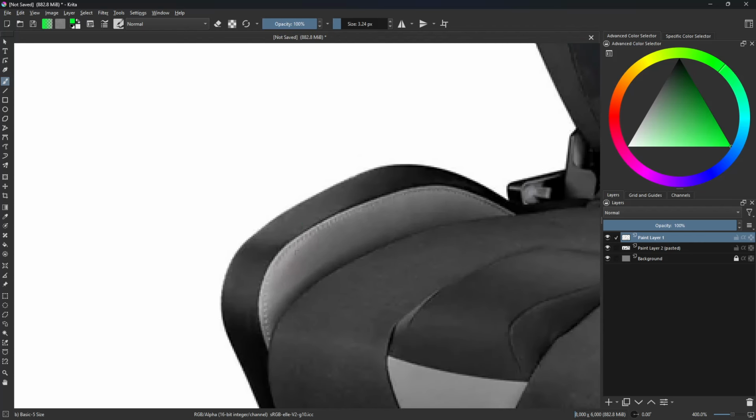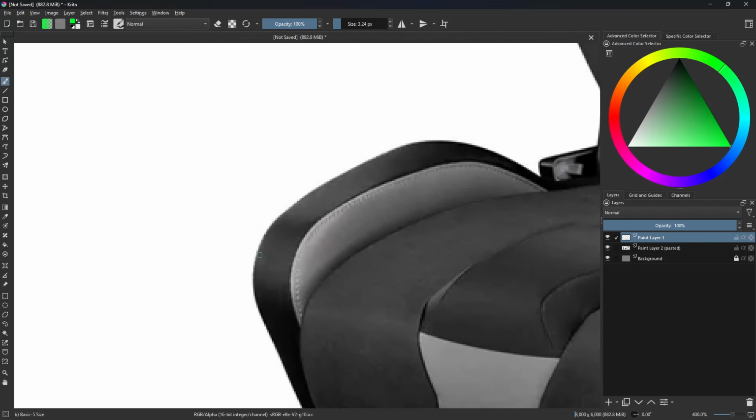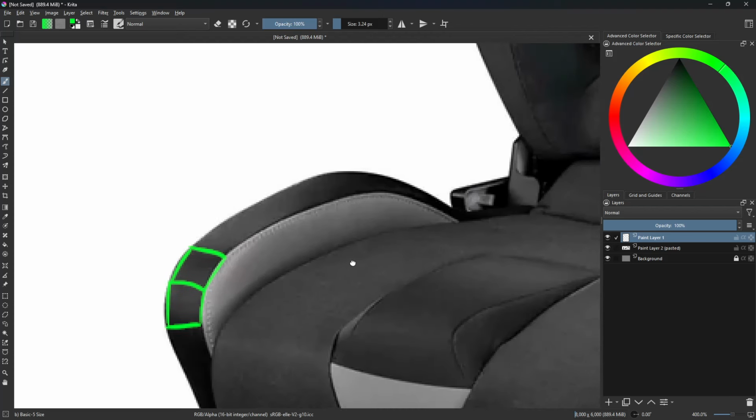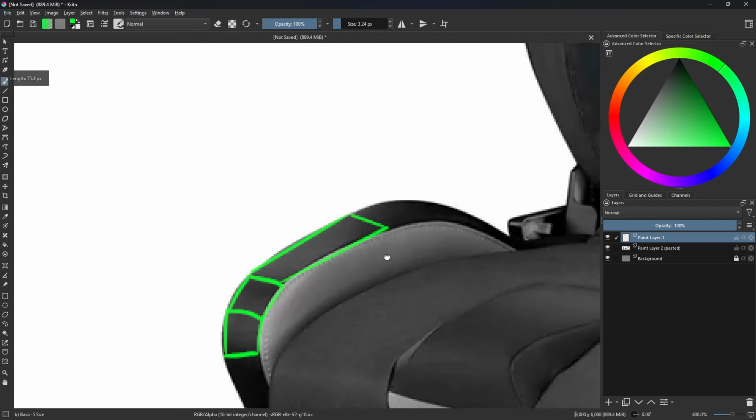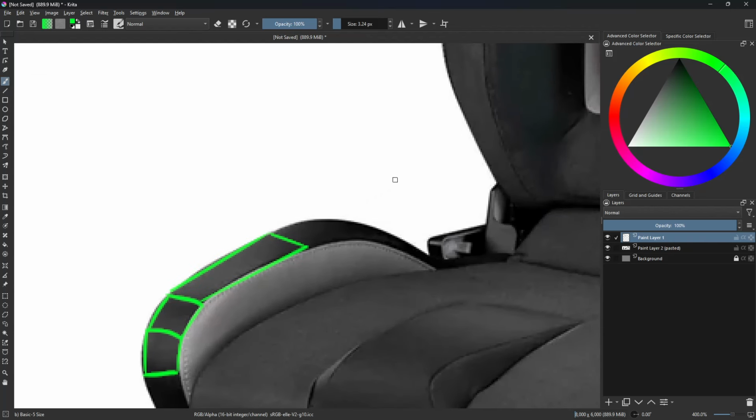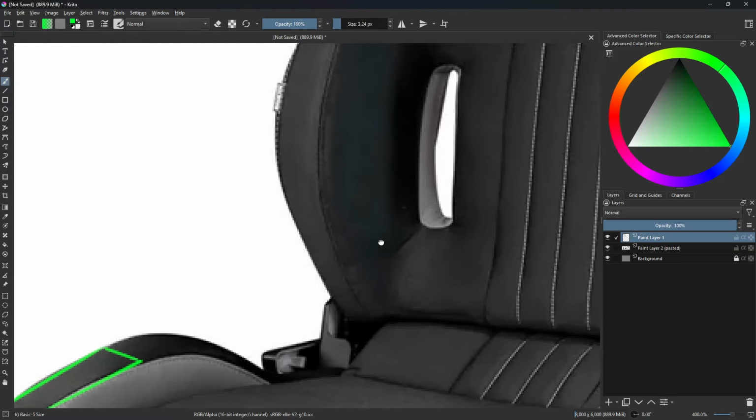Now, if you're going to do subdivision surface modeling, you know that you need 3 edges to hold a curve. So when you see curves, you should be thinking 3 edges, right? And that'll be your setup there for the most part at its most basic fundamental levels. And so you should be identifying areas that might be a little bit more flat, thinking of those as planes perhaps, right? Okay, and then that's all you're doing for these.